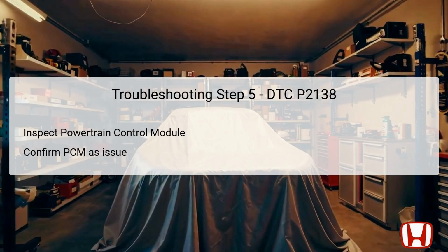If all previous inspections check out as normal, the final step is to examine the powertrain control module. The PCM, which plays a fundamental role in controlling engine parameters, may sometimes be the source of the problem. To confirm this diagnosis, diagnostic testing will need to verify whether the issue lies solely with the PCM. If the PCM does not respond accordingly, after ensuring all other components function properly, it indicates that there may indeed be a malfunction within the PCM itself, which would necessitate further action, such as reprogramming or replacement.